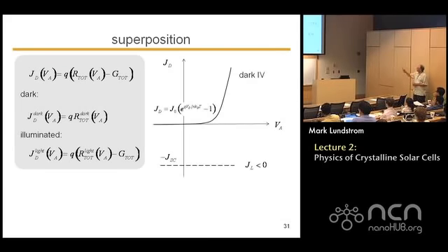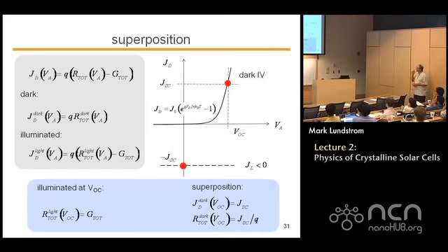My open circuit condition, for example, will occur when the diode current in the positive direction is equal and opposite to the light generated current, which is negative. And I'll add the two and I'll get 0 current. That seems very reasonable, okay? But it's really a little hard to justify. Under illuminated conditions, the total recombination in the light is equal to the total optical generation.